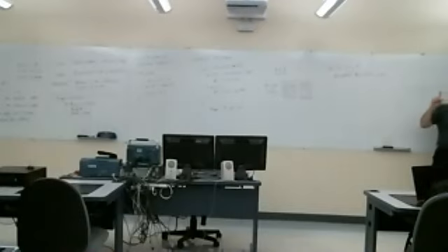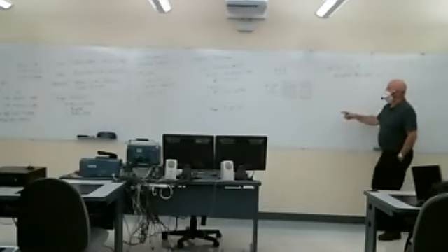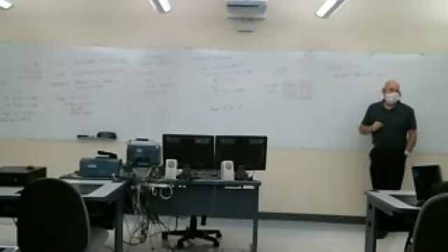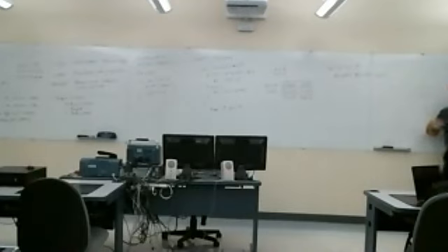But what does ORing with 1 do? What's A ORed with 1? It's always 1. So it doesn't matter what bit 6 was, whether it's 0 or 1, I don't care. The output would have B6 as 1 and all the other bits unchanged. So this is another common operation that we'll be doing when we need to set a bit in a particular register and leave all the other bits unchanged.